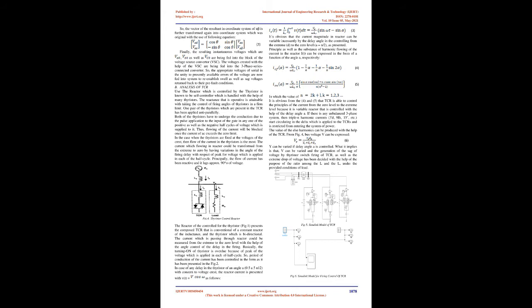See supercapacitor modeling. Though there are several advantages, there are disadvantages related to the UCs, which one will be able to take care of during control design. The energy stored with respect to weight in first generation UCs is lower compared to electrochemical batteries. The amount of energy stored brings variations in the voltage. To make sure that the energy is stored and recovered efficiently, switching equipment and electronic control are essential.